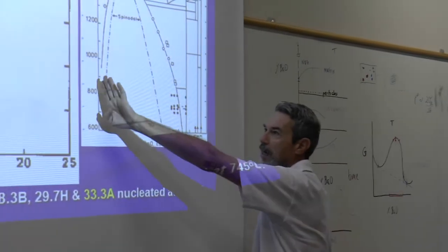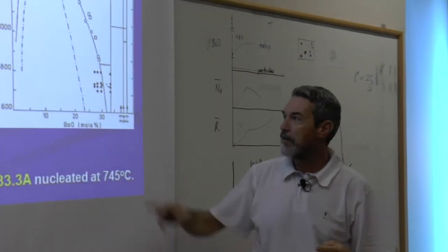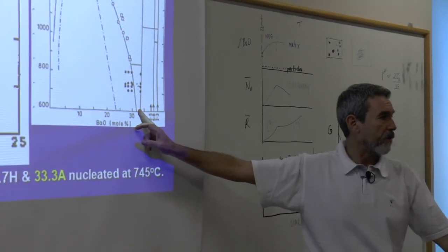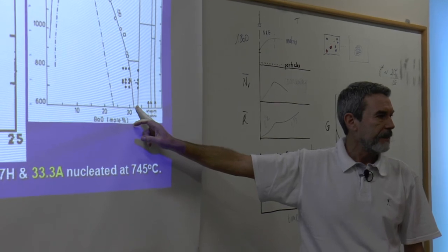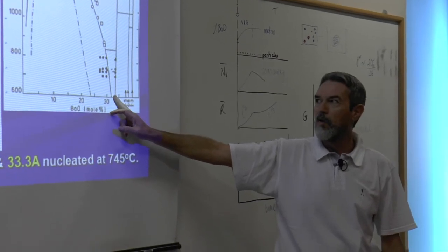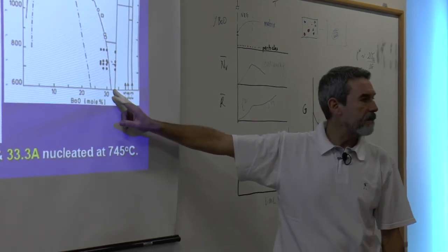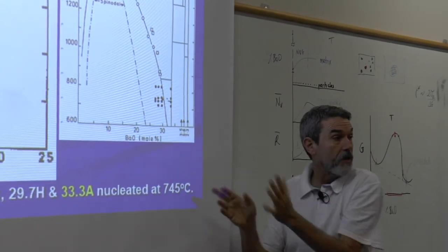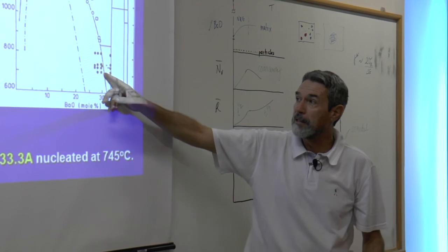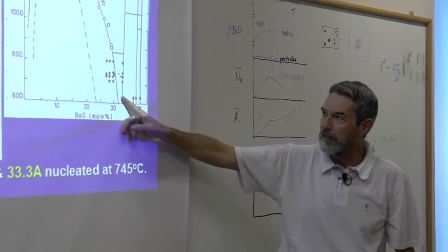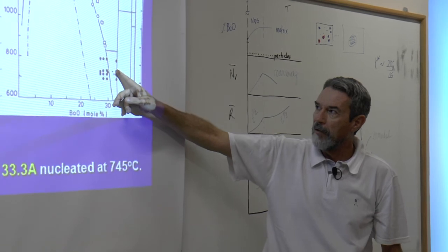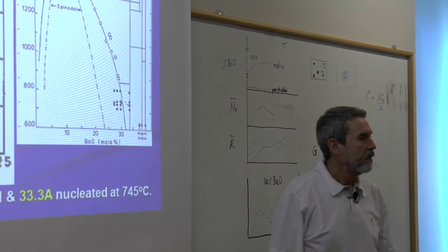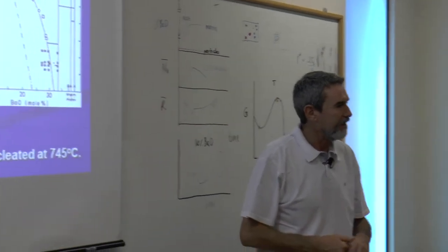So to this side here, the only equilibrium phases are barium disilicate and one of the silica phases, or quartz, or tridymite, or cristobalite. Only them. There is no solid solution, nothing in this particular system. Some systems have solid solution formation, but not this particular system. At this kind of temperature, the only crystal phase is barium disilicate. If you go to higher temperatures, there are polymorphic transformations, as you know, of the same stoichiometry again.